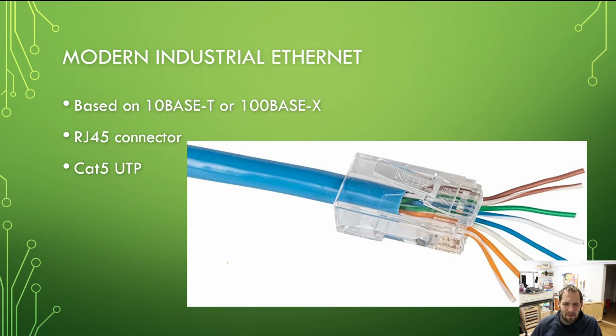Now, 10BASE, 100BASE, again, the biggest issue we have in industrial networks is not our transfer speeds. It's how long it physically takes for me to send a packet from one location and for that to get delivered to another. It's not, oh, we have a throughput of 100 megabits per second. That doesn't matter. We're probably only sending like 2 or 3 bytes per transmission.